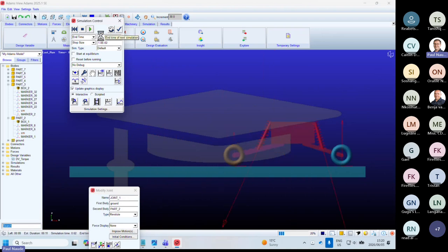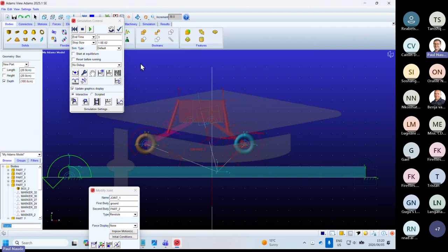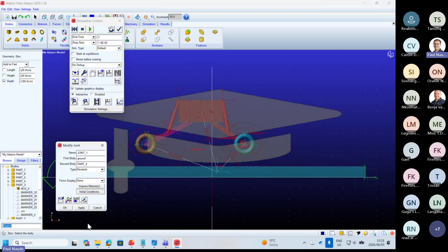So this is what it's going to look like. And I am going to add a little box again. But this time around, I'm not going to create a new part. I'm going to create the box to an existing part. And you will see that over here at the bottom in the text, it says select the body. So I'm selecting this body.